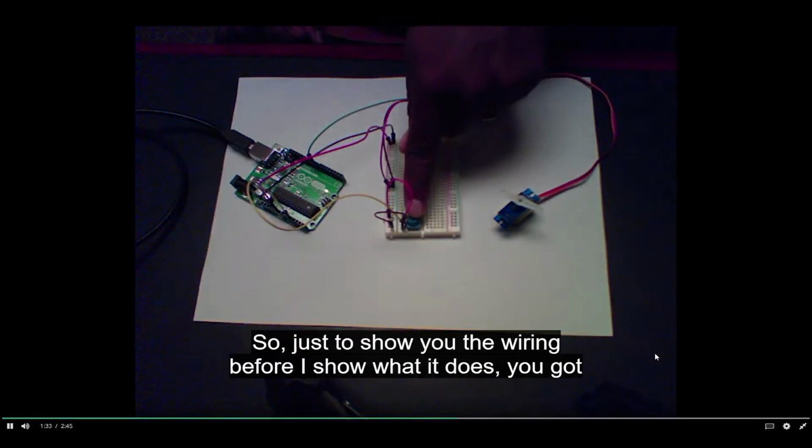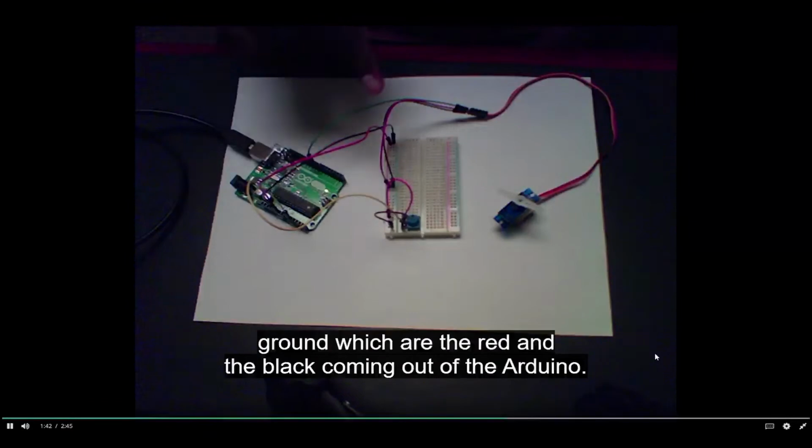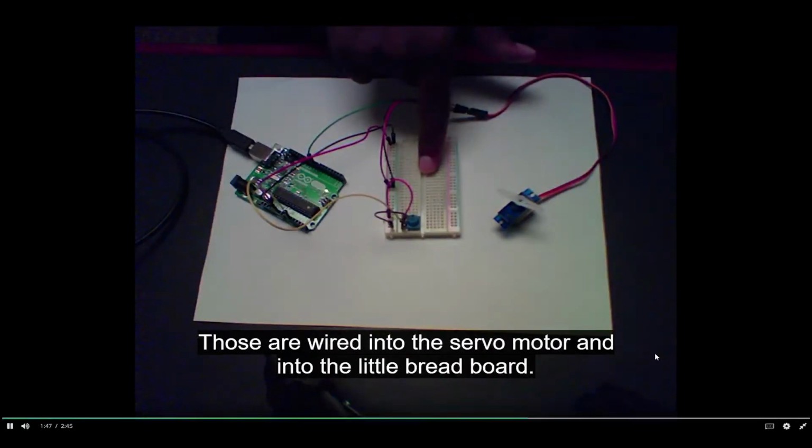So just to show you the wiring before I show what it does, you've got the potentiometer wired to, actually, let's start with the power and ground. Everything's wired to power and ground. So we've got power and ground, which is the red and the black coming out of the Arduino. Those are wired into the servo motor and into the little breadboard.